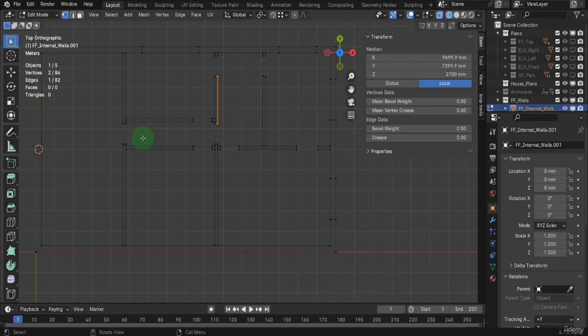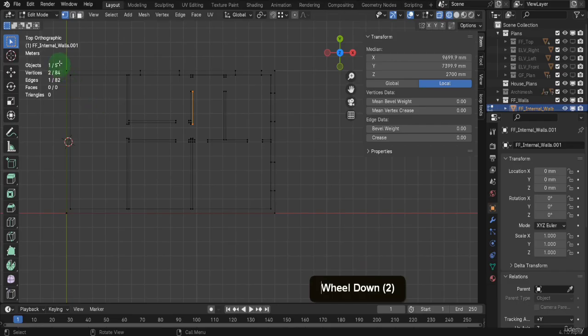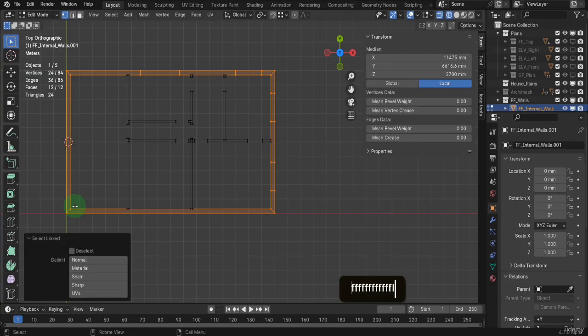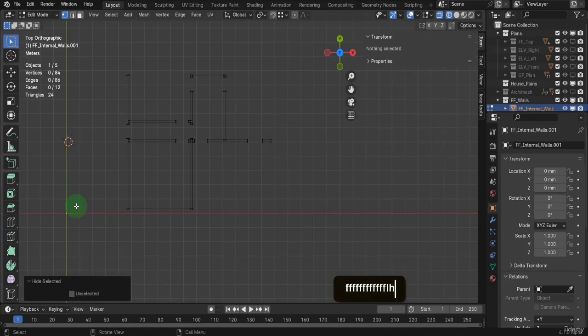We can start with the external walls. Let's drag select the 4 side vertices here. Press F and create a face. Select the front 2. Then press F again and continue to fill forward back to the start. You may have to manually select and fill in if fill forward fails. Usually overlapping vertices are the culprit. Hover on the external walls now and press L to select linked. Press H to hide.